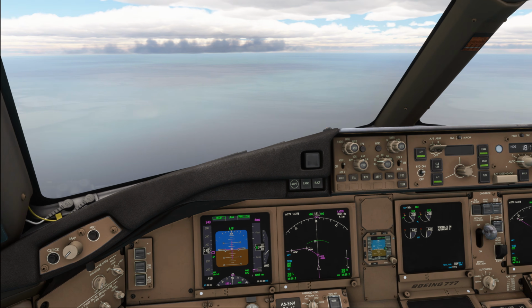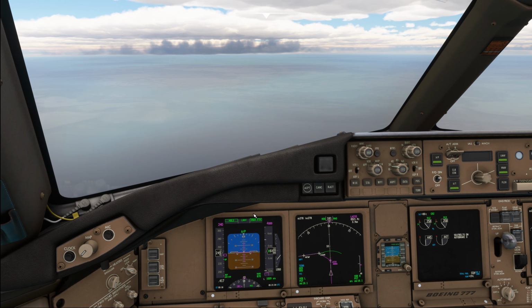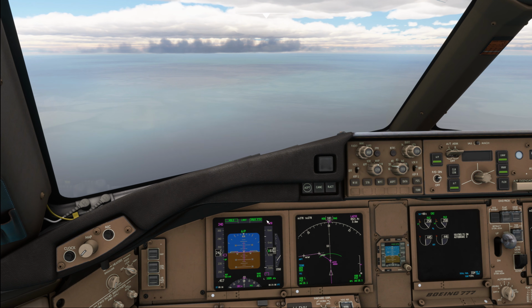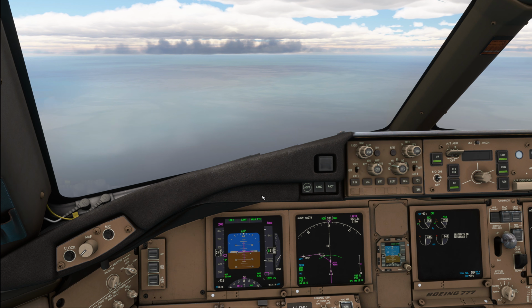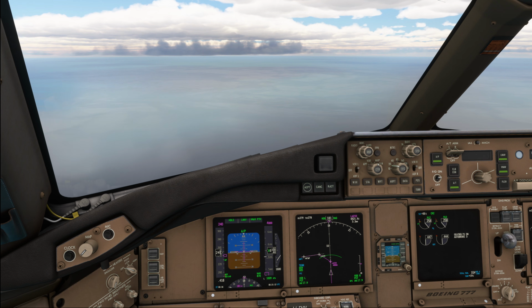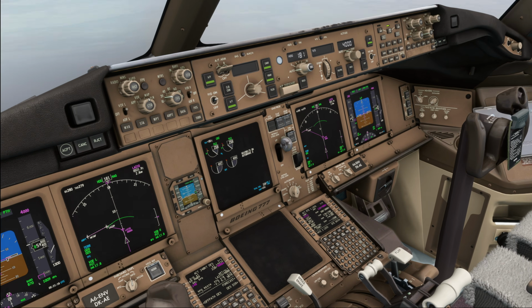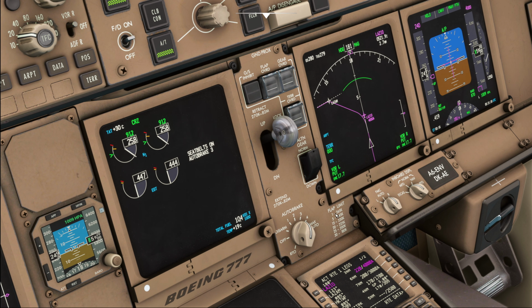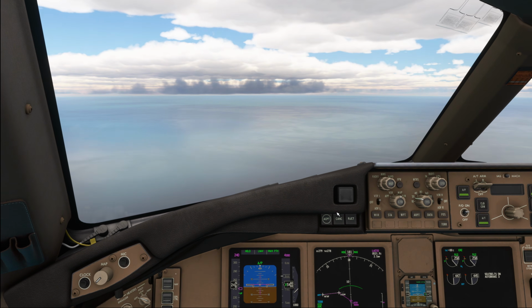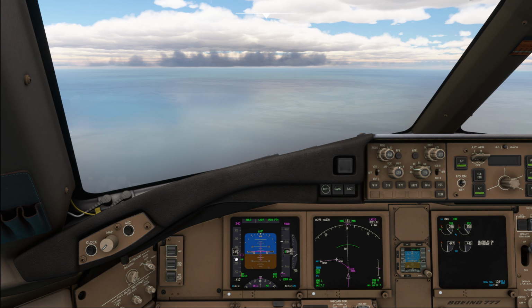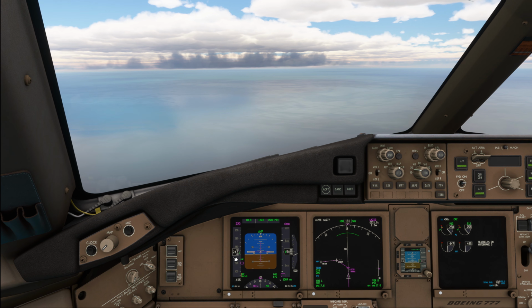Once the FMC is on approach logic, you can open the speed window, and the airplane is going to remain within VNAV path. Now, the easiest way to force the airplane into approach logic is to get the flaps out into the first setting. You've got a rather high flap limit speed here, 165 knots for the first flap setting, so normally you are going to have that option available to you pretty soon.